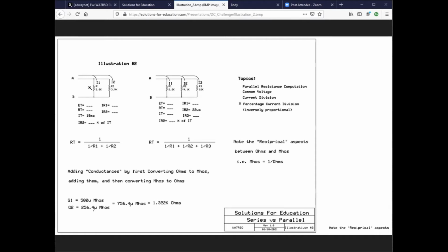What you really got here, you say, I got two resistors in parallel. But wait a minute, look at it from this way. You have two conductors in parallel. And the total conductance is simply going to be the summation of the conductive values. You say, well, I thought we were doing parallel resistors. Yeah, but they're also parallel conductors. So down here, this formula in reality is conductance of the first resistor adds to the conductance of the second resistor, and you have the total conductance.